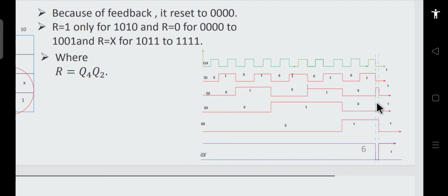Okay, so when this temporary state happens, in this case only the counters get reset. Let's see, if this happens, then in which state does our counter remain? Initially it is in the 0 0 0 0 state, where this is our MSB and this is our LSB. So Q4 is our MSB and Q1 is our LSB.